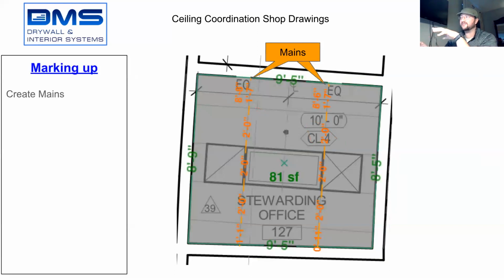So they've compensated for that and laid their ceiling out a certain way. In this example, I did the same thing. On a polyline, you just click, click, click to create a straight line, and it will automatically tell you your segments and your full dimension. As you can see, this part of the ceiling is 8 foot 8, and the length of this main tee is 8 foot 6. So this ceiling has a slight tilt to it and is shorter on one side.